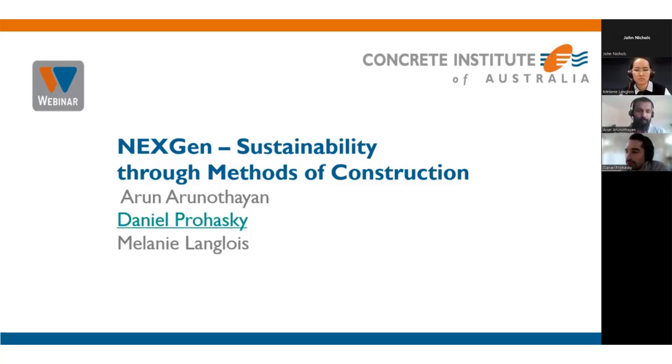Yeah, absolutely. So the geopolymer that we're using is high early strength. So within 18 to 24 hours, we can demold the panels. From a production perspective, from a precursor perspective, this has some trade-offs. To achieve that high early strength, the open time is reduced, which causes a challenge in how you can get the material into the mold quick enough. But the benefit is that you can demold quicker with larger panels.